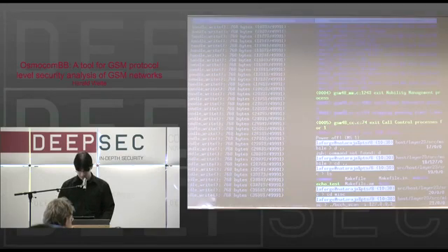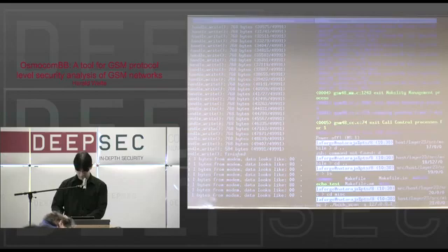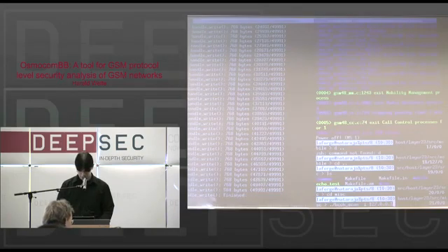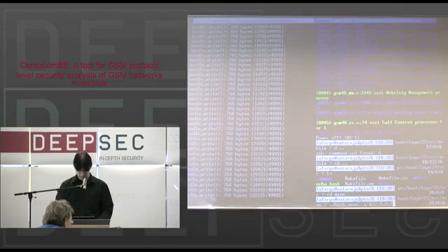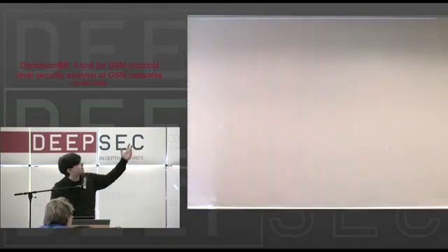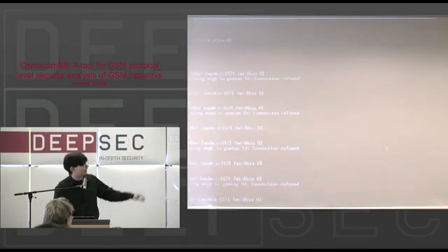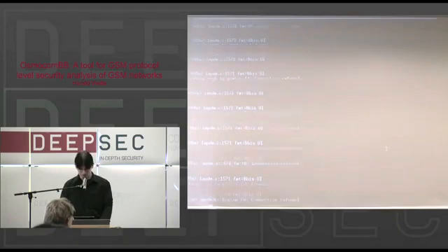There we go. Okay. So now I'm starting this scan. It's scanning over the GSM. Oh, the projector, it's way too bright for the projector to have any decent contrast. It's scanning over the frequency band, and it's identifying all the various cells that are there. It's receiving the broadcast messages from various cells. You will see lots of 2B again here, right? It's the same kind of messages that Carsten has been showing. Now we're seeing them from a phone.